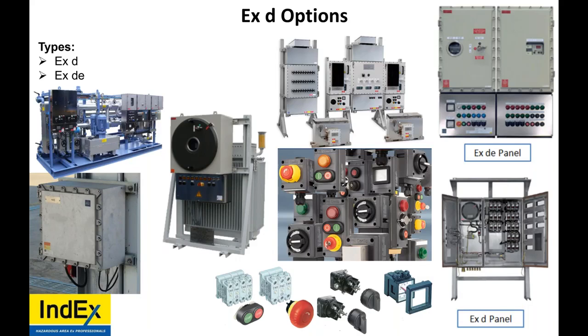And then while it's under load, during factory acceptance testing, they would put it under 100% load, and perhaps apply faults and see what temperature that device can get up to. Then they would certify to what temperature that would be good for and any other conditions of use.